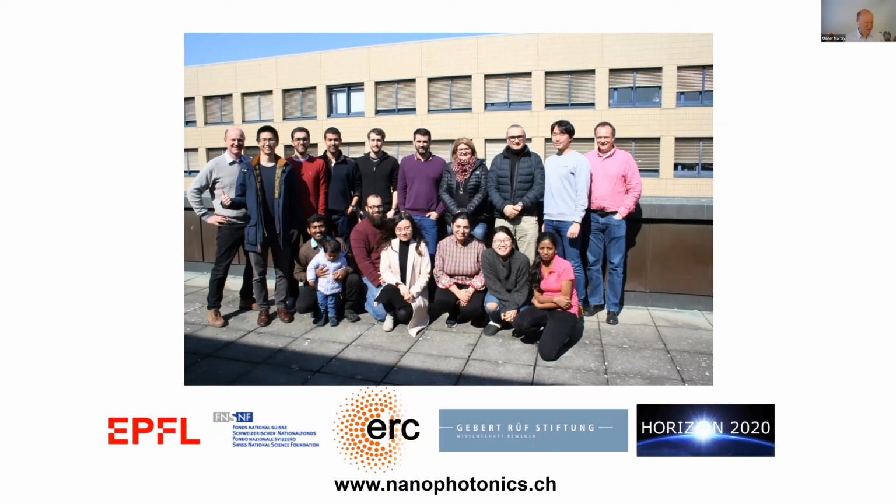It turns out that both silver and aluminum have the same kind of crystal parameters, so they go very well together. As a side note, in developing this process, we have also observed that we can stabilize silver. If you make sure that during the evaporation you have almost no water in your system, you can keep your samples for months afterwards and they don't deteriorate. Also, we have a paper that describes it.